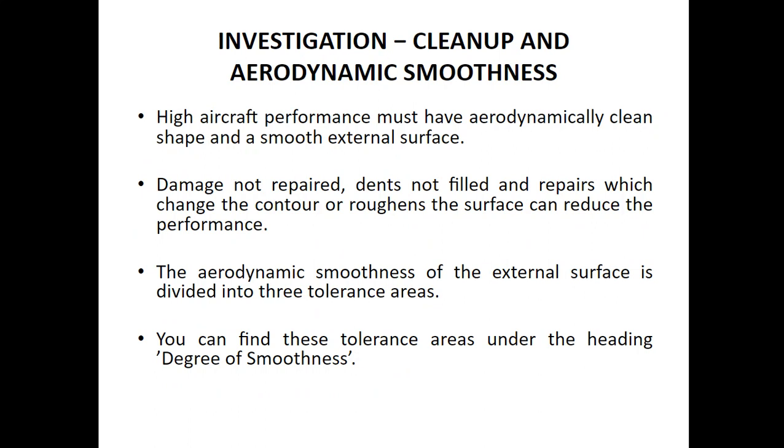So you need to look at the aerodynamic smoothness. The structure repair manual will give you the area of the smoothness, the tolerance and the allowable. High performance aircraft must have an aerodynamically clean shape and smooth external surfaces because of drag. If damage is not repaired it may not fail, but a repair will change the contour, roughen the surface, and reduce the performance.